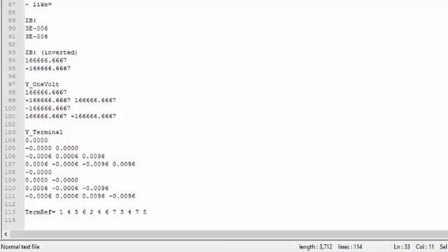In this case, ZSC for each single-phase transformer within the three-phase transformer model must be calculated such that the total losses are equal to the value specified in the % load loss parameter. Then, this impedance can be calculated considering that each of the single-phase transformers will handle a third of the total three-phase power of the transformer.